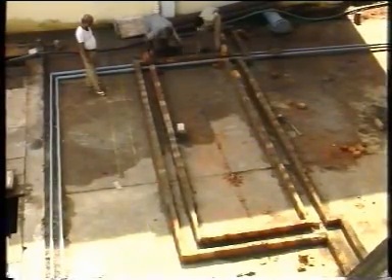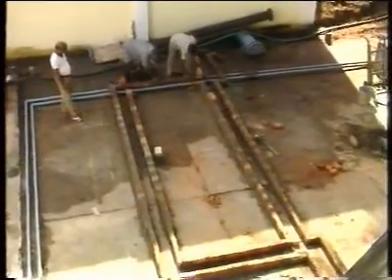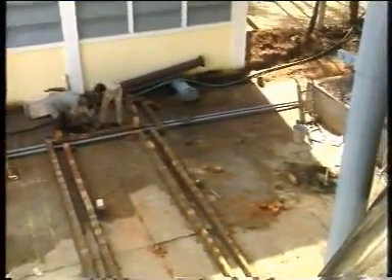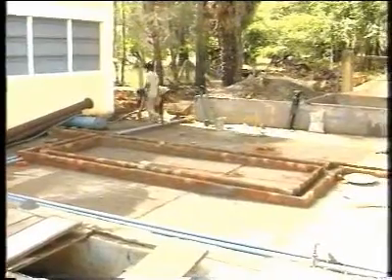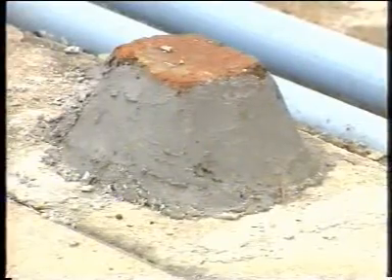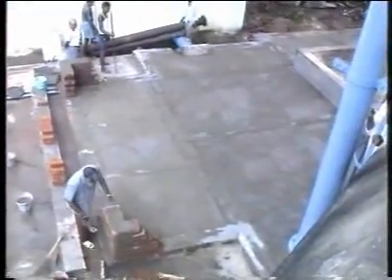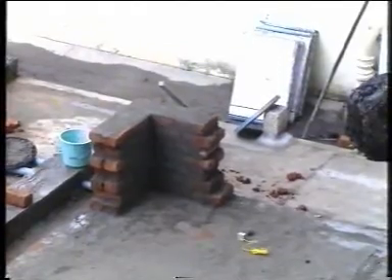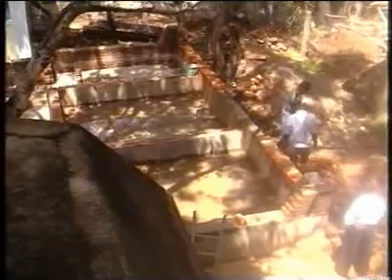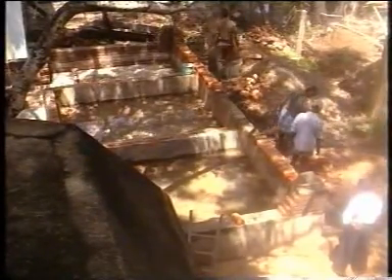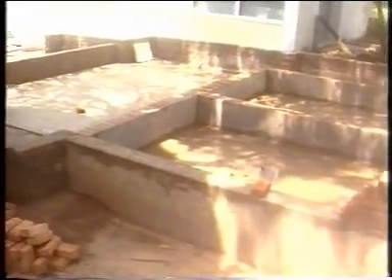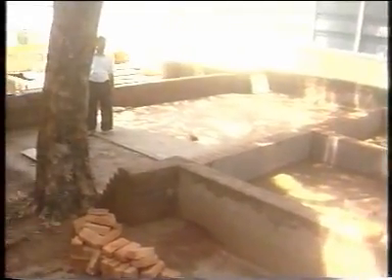Before the model construction is actually commenced, the layout is marked precisely on the level ground, and precise reference levels are marked and benchmarks located. Brickwork in cement mortar is then proceeded with. Water supply, pipeline and location of main control valve is then fixed along with an inlet tank of sufficient capacity.